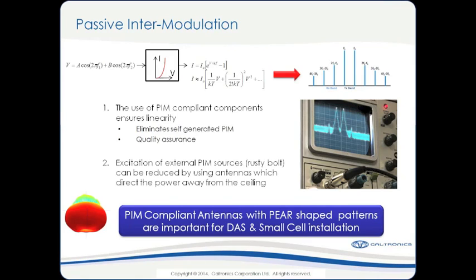This is just something from the internet, but you see two tones, and then on the scope you see the noise floor, and then you see the intermodulation products popping up above the noise floor. Now this is important because the noise floor is significant, and the amplitude of those peaks relative to the noise floor is significant. Obviously, if those peaks were below the noise floor, then the intermodulation wouldn't be so much of an issue.